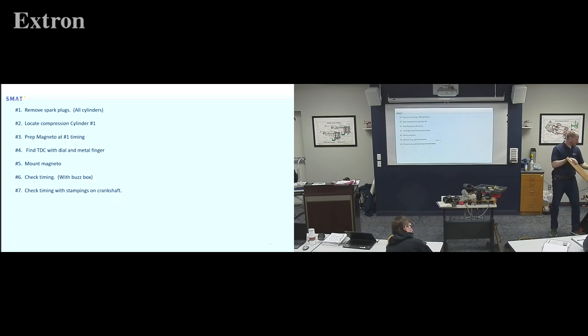Now, the book says I could take this out, but Case wants to make sure it says 39 this way. Hey, sure enough, 39. So that means I'm headed towards top center, and I could even check. Oh, good, compression stroke yet. Top center, compression stroke.